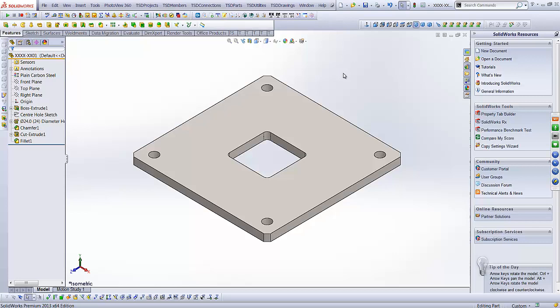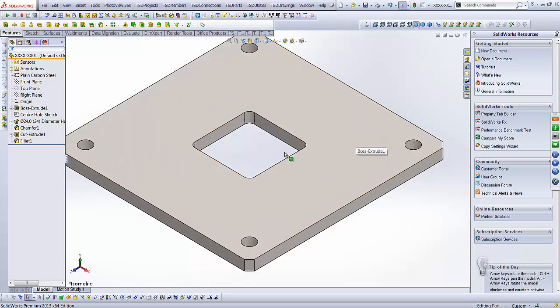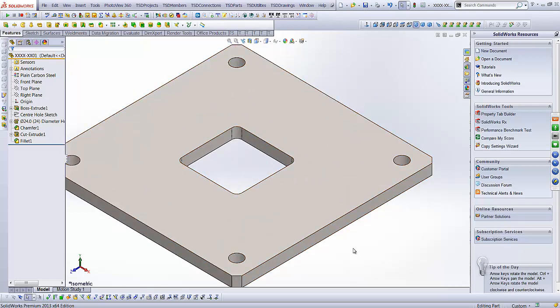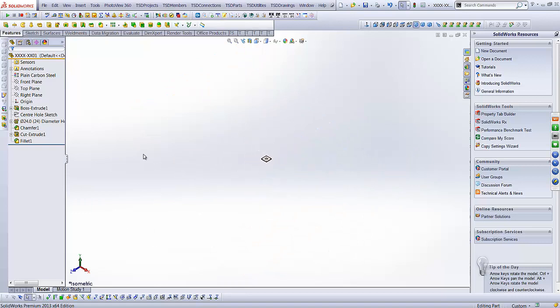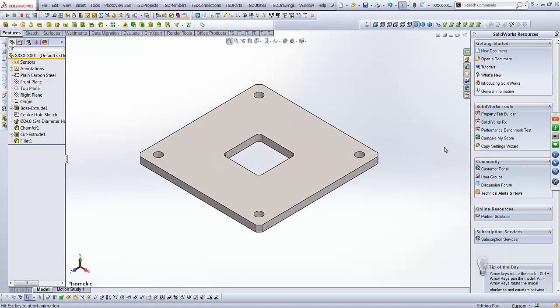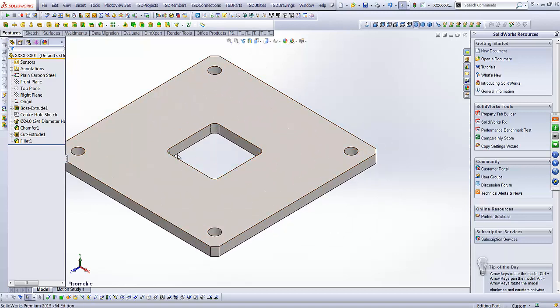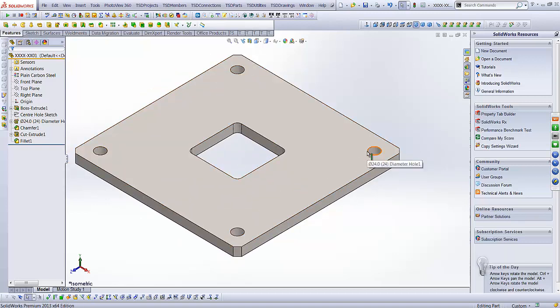When you add it to the library or upload it to the library, it takes a snapshot of the plate in its current position. Okay, so you can zoom right in and get the plate, or you can zoom right out and not get anything. So you get this little picture. Now I recommend you zoom right in, keep it over to the left because that's where the snapshot is. Now the actual bitmap snapshot that gets created is a 200 by 200 bitmap, and you want to make sure that you've got your picture pretty much square in a 200 by 200 bitmap.